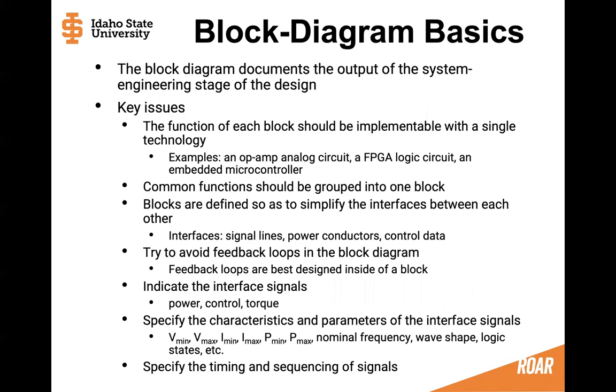In the block diagram, you want to be able to break the whole system down into the subcomponents. The function of each block should be implementable with a single technology. So when you've broken down your pump into multiple subcomponents, each subcomponent block should have a single thing that it does, using a single technology. So maybe one op amp, one FPGA, one microcontroller, something like this. A single technology implements that block.